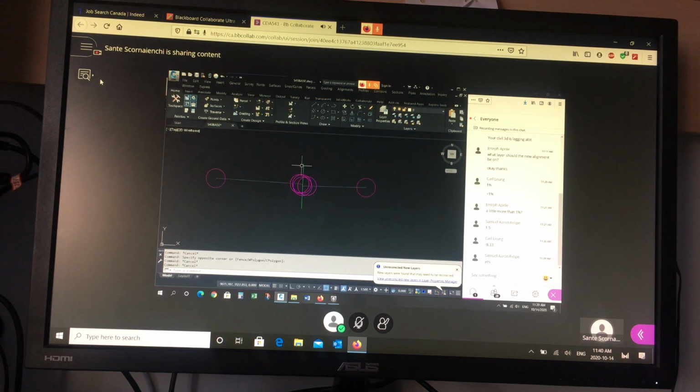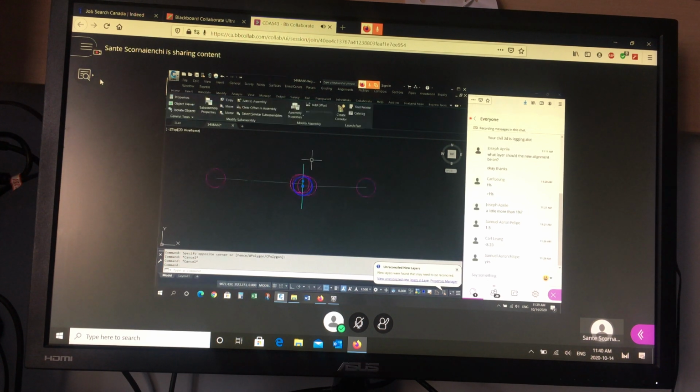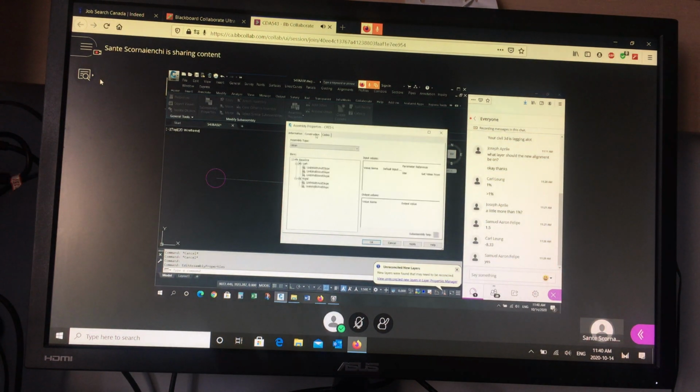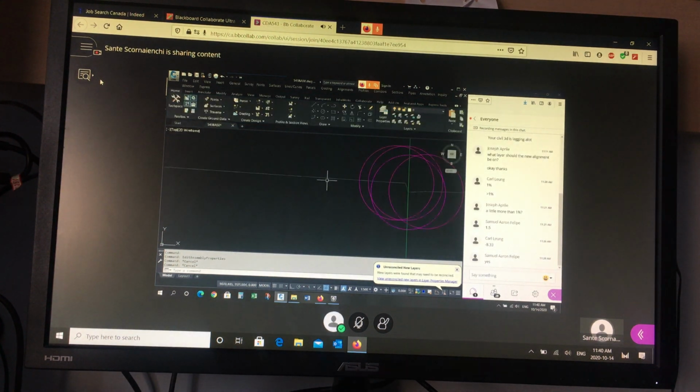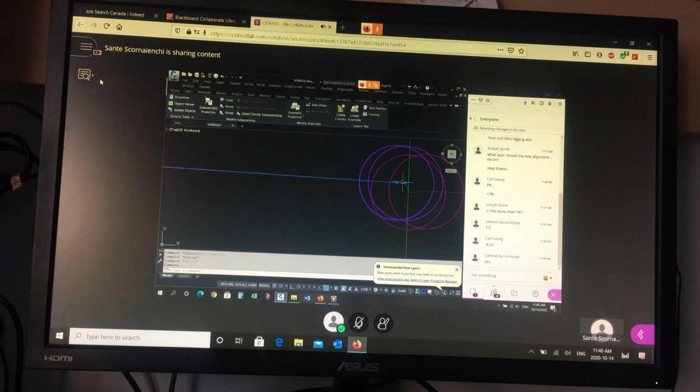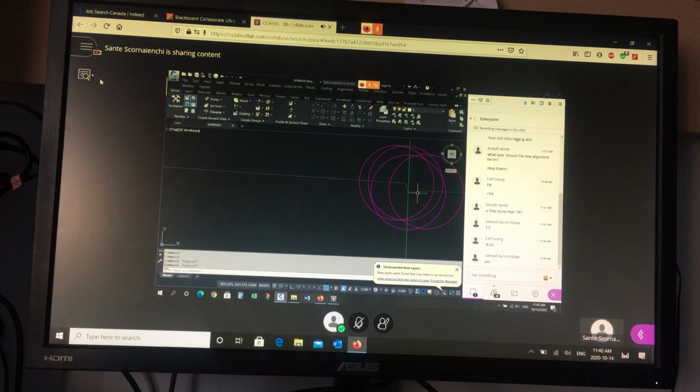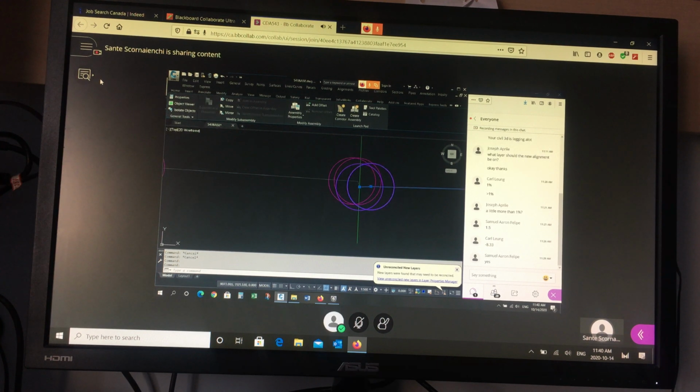Now, when you look at this assembly, I'm going to right click and go to my assembly properties. If I go to the construction, you'll see 1, 2, 3 links on one side, and you'll highlight them here. You'll see the boulevard, the top of curb, and the face of curb, and then on the right side, you'll see the gutter and the pavement. This is the pavement line here. So there's 1, 2, 3 pieces on the left, and 1, 2 pieces on the right, okay?